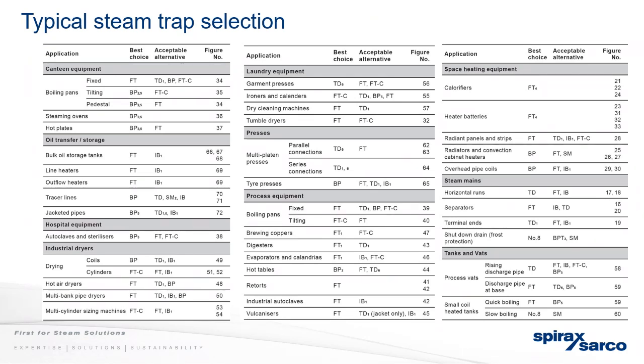The challenge you have with a ball valve for isolation is if you have isolated, you have steam behind it, which is cooling and creating condensate. Because they quick open, because they're only quarter turn, if you're not careful, you have the chance of introducing a large slug of water to run straight down your system. With the bellows seal valves, because they're wind up and wind down, it's less likely. It can still happen, but it's less likely.